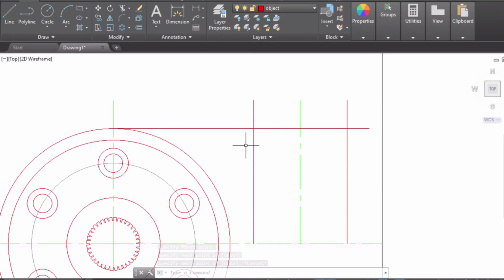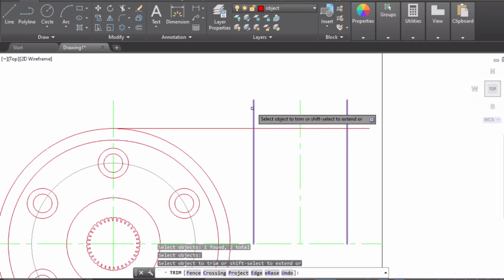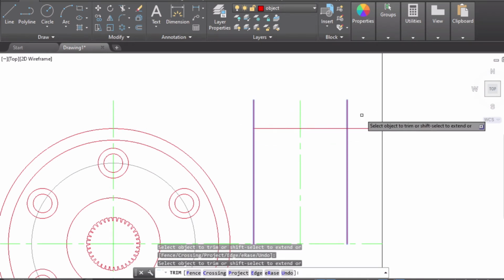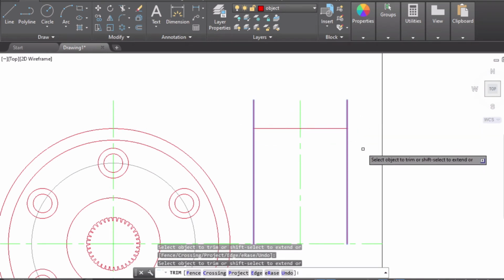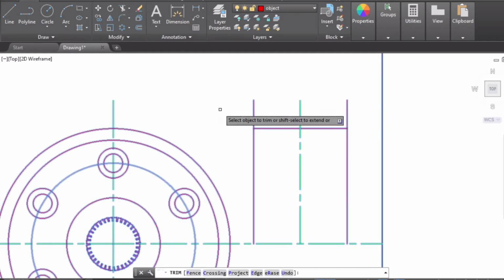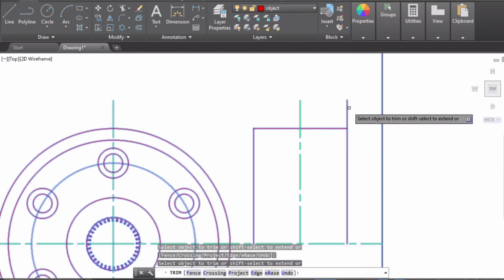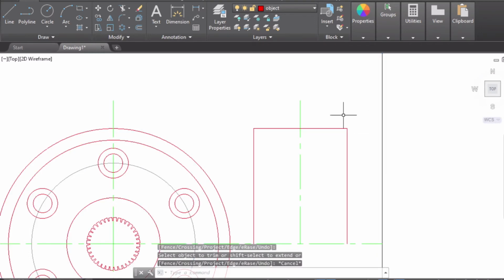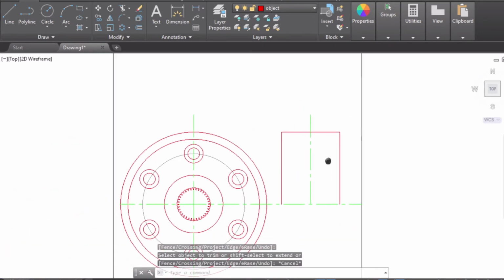And once you finish, you can trim out the remaining portions. So I need just a connection here. Take the trim tool, select these two, enter, and you can trim out these extras on the top here. Control A again, choose the trim tool. I would like to delete this as well. This is how you can trim off.